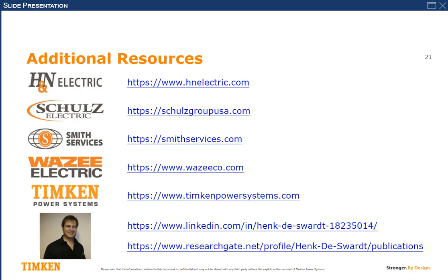That's a good question. I've honestly not seen a lot of people use it, because ultrasound is looking for ultrasound, obviously. The way I've seen people actually use it was on DC motors, where they use it to check that the commutation is done correctly. But on a DC motor, you can also see sparking on the brushes, so I didn't find it to be that useful.